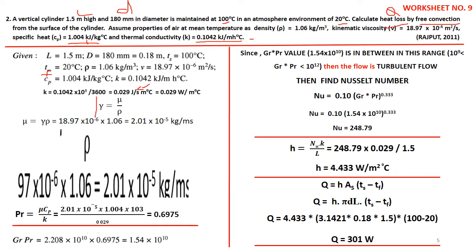We know this relationship, this formula. I think you remember, in forced convection we discussed this formula. What is the relationship between kinematic viscosity, dynamic viscosity and density? Okay, so this is the relationship. In the problem, kinematic viscosity is given, right? Then we want dynamic viscosity, then only can I find Pr, right? So here itself I am going to convert. So mu is equal to this one into this one, cross multiply. So kinematic viscosity is given, density is given, so multiply both the things, then you will get mu. Okay, 2.01 into 10 power minus 5 kilogram per meter second.